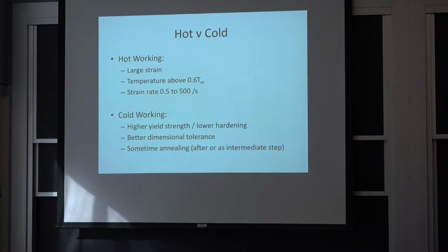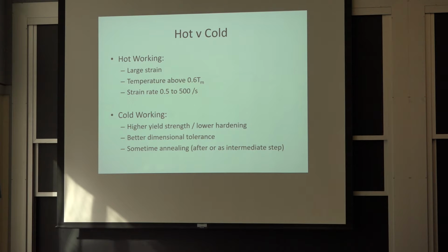So a similar effect of rolling here, because rolling, you can do it hot. You can also do it at ambient temperature. When you do it hot, your advantage is you're not limited by strain because you have this recrystallization, recovery of the steel, so it doesn't feel like it's getting deformed. It's healing itself at the same time as you're deforming it.